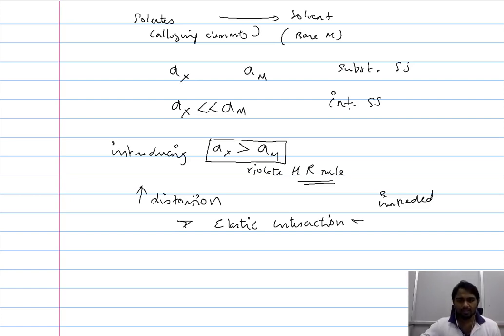Now, all the discussion so far is confined to the substitutional solid solution, and particularly when the size of the solute atom violates the Hume-Rothery rules. However, the same is also possible when it is within the Hume-Rothery rules, and since when you comply with the Hume-Rothery rules the amount of solubility increases, you then have an increased amount of solute atoms present and an increased amount of distortions, but these distortions are rather dispersed, and therefore the effect of the distortion is more pronounced when you violate the Hume-Rothery rules.